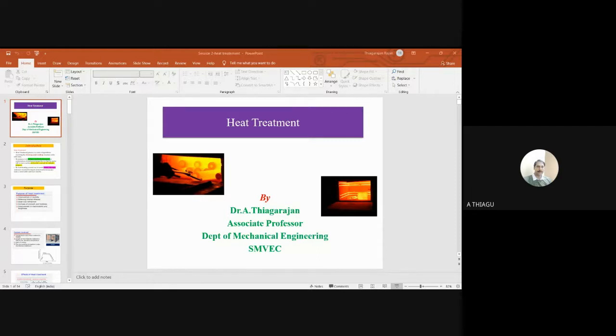For example, 0.4% carbon steel is applicable for the flame hardening process. I will show the picture so you can understand. Now you can look at the diagram. We have to adapt this process for surfaces such as gear teeth, wheels, shafts, mill rolls, cams, spindles and machine tools. Quite interesting, with many applications.